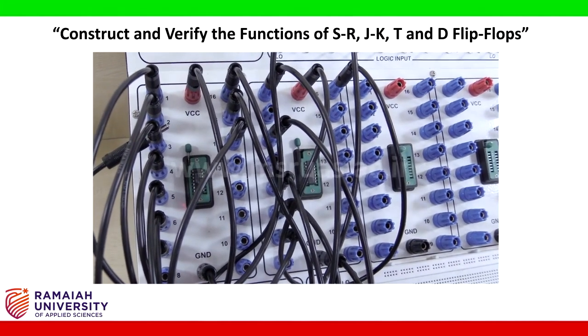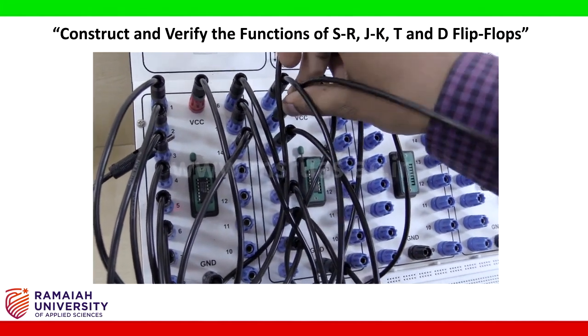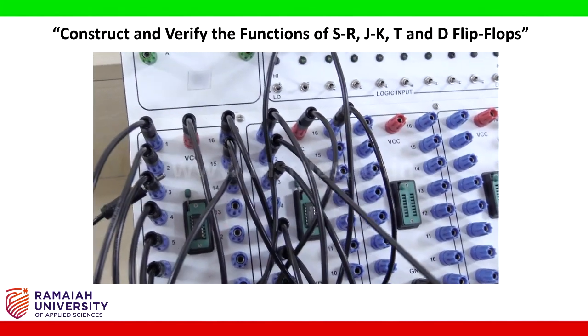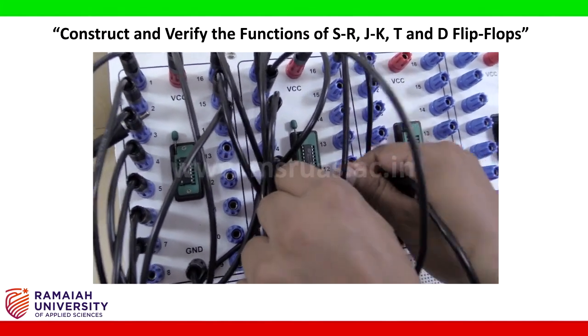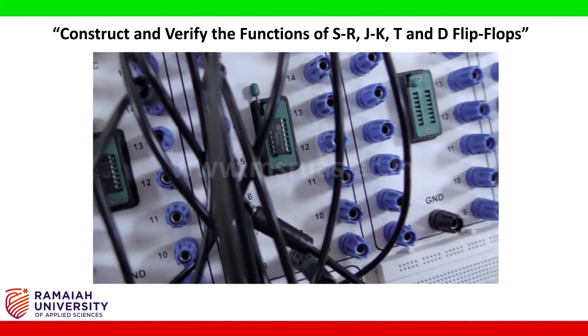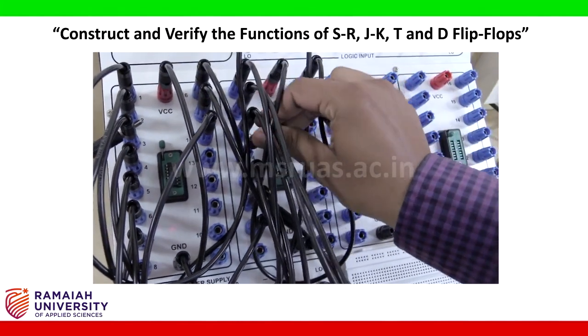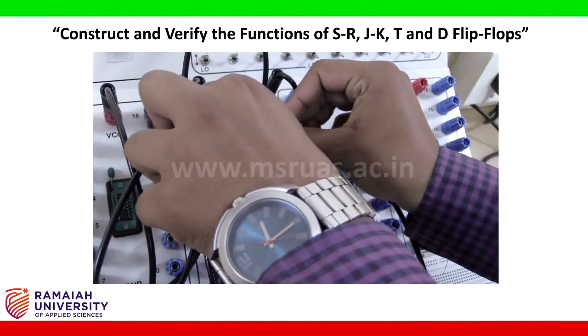Then pin number 2 of the second IC base is connected to pin number 6 of the same IC base, that is here. Then pin number 4 of the second IC base is connected to pin number 3 of the second IC base itself.